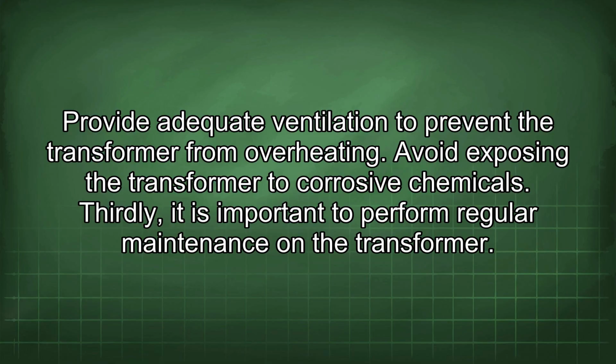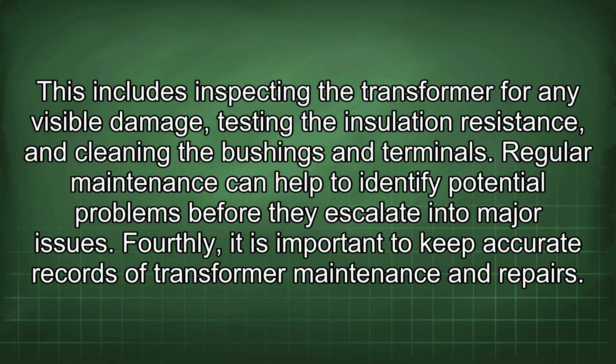Thirdly, it is important to perform regular maintenance on the transformer. This includes inspecting the transformer for any visible damage, testing the insulation resistance, and cleaning the bushings and terminals. Regular maintenance can help to identify potential problems before they escalate into major issues.